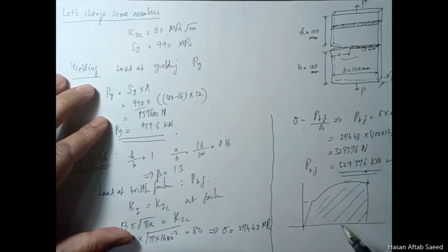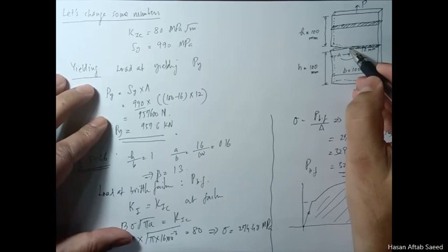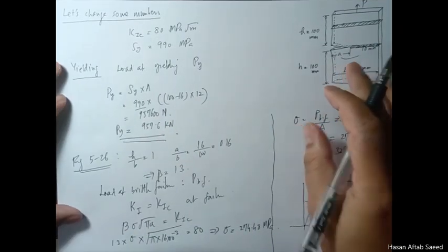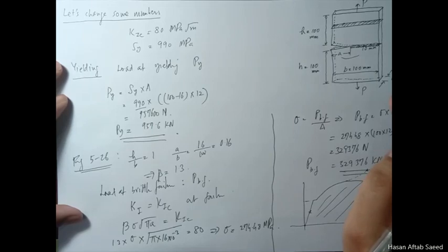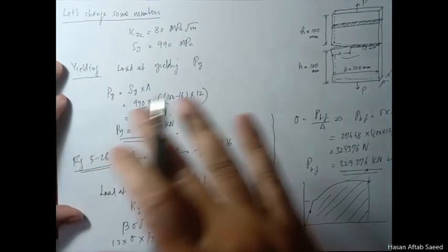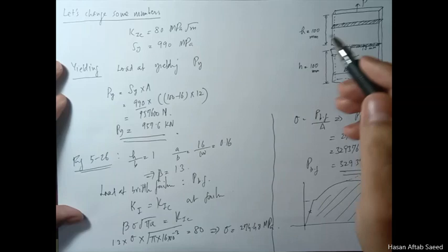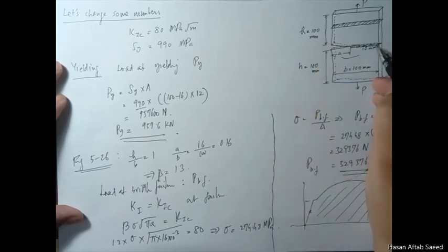Here, what is happening is it broke here, somewhere here. There was not even yielding there. The yielding which occurs in these cases when the crack propagates is a very minor, minute, local kind of yielding, and it doesn't take the whole energy required to yield the whole area first, and then up to a certain level of the depth, and then followed by a strain hardening and all that sort of thing.